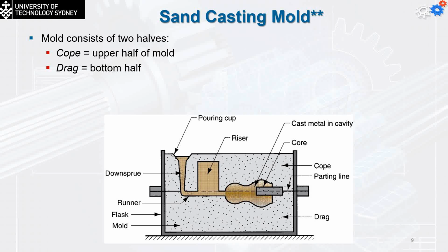Now this riser, when I'm going to fill the metal in the cavity, sorry. When it's going to be filled, I'm going to have some cavity here. So some of the metal is going to be going up in the riser. It's going to have some pressure here. As the molten metal starts to solidify and shrink, the molten metal here starts to pressurize and push to fill the cavity generated around the shrunk part. And thus I'm going to fill everything, and I'm going to overcome the problem of the small dimensioning of the part.